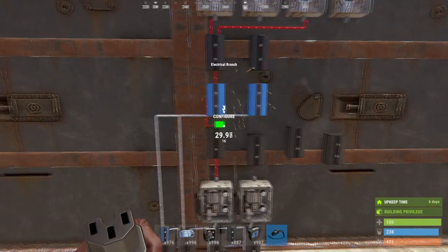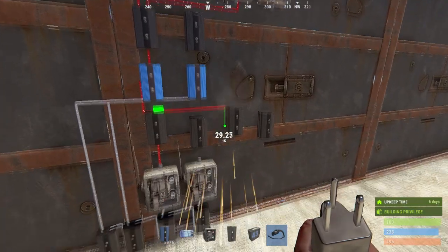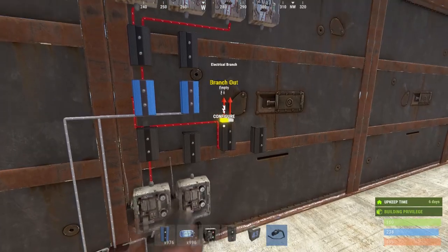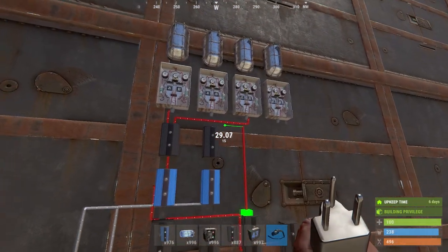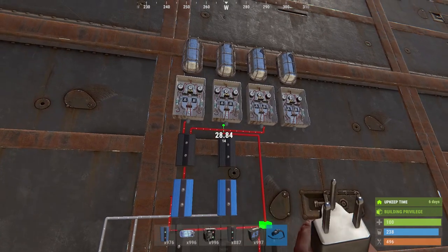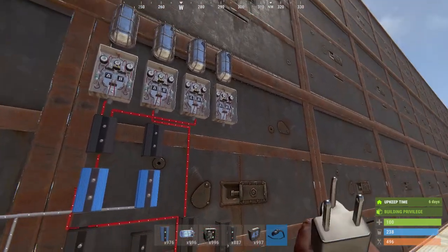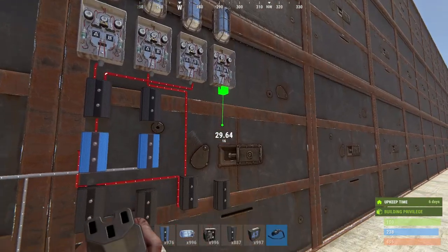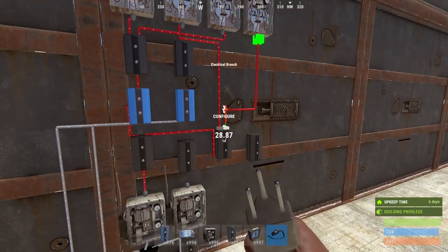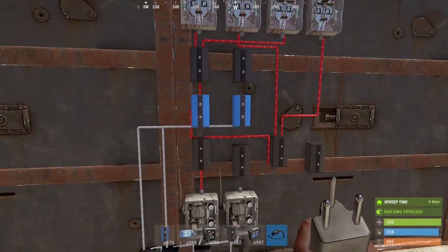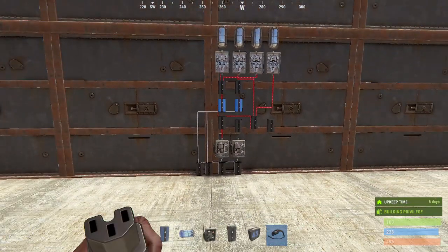Then, carrying the A line over further to the next branch, you'll take the outputs and carry it to AND gates 2 and 4. Now take a step back to make sure everything's right.